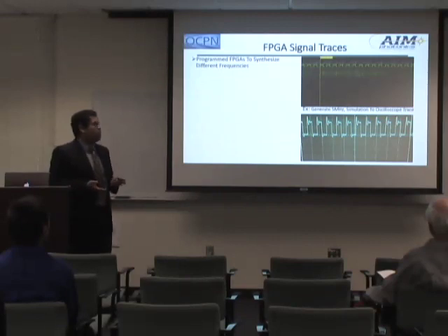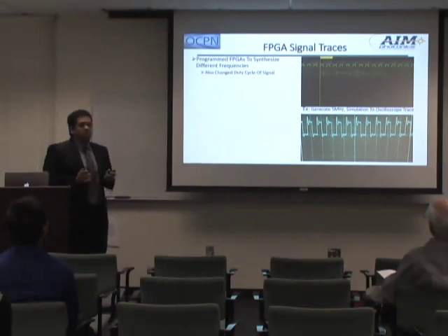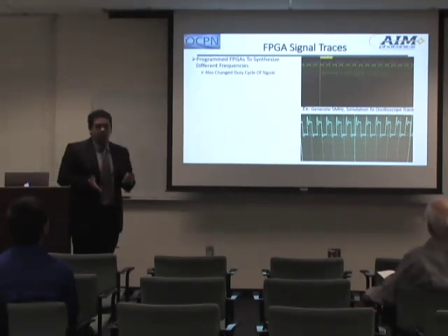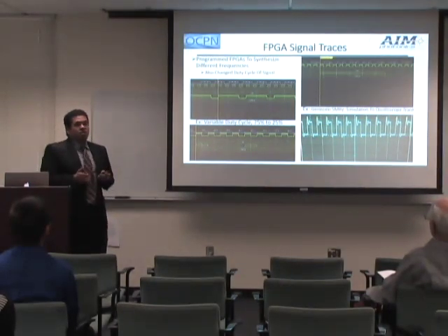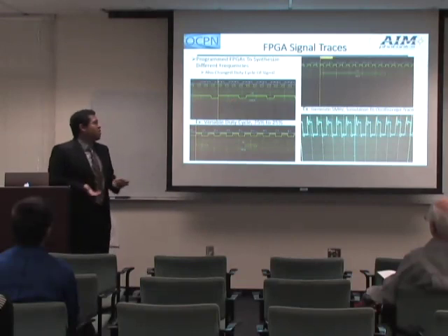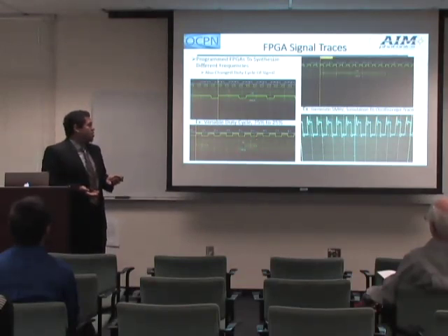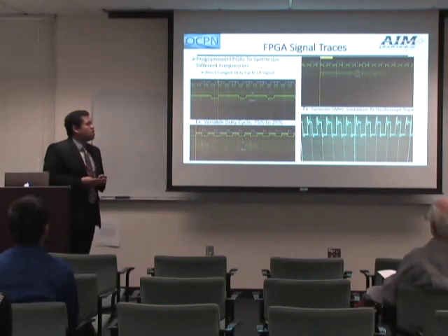Another thing that I've also worked on is changing the duty cycle of the signal. The duty cycle basically indicates the amount of time that the signal is left in an on period versus how long it's left in an off period within its natural cycle. These two are simulation traces where I've used a standard 50% duty cycle wave. So in its natural frequency, it's on for half the time and off for half the time. I shifted it so that it would be 75% on at the top and 25% on the bottom. Changing the duty cycle can actually affect the power consumption of the device as well. So it's just something that I've also worked on.